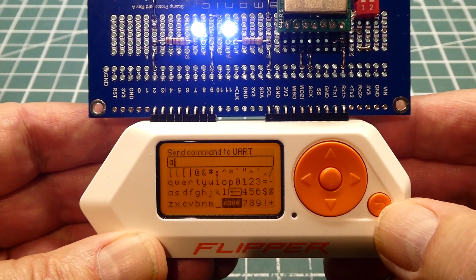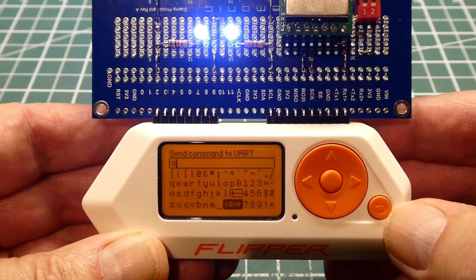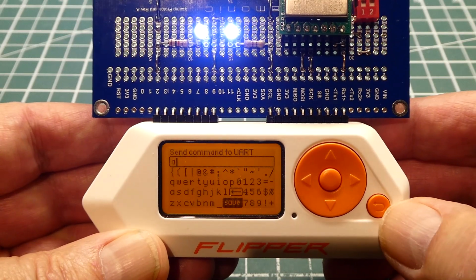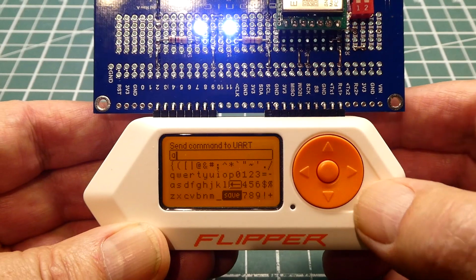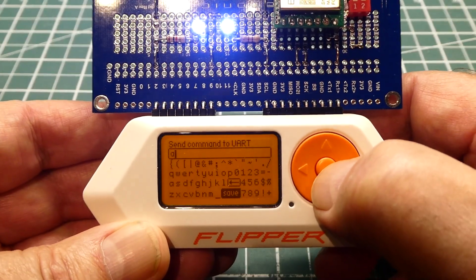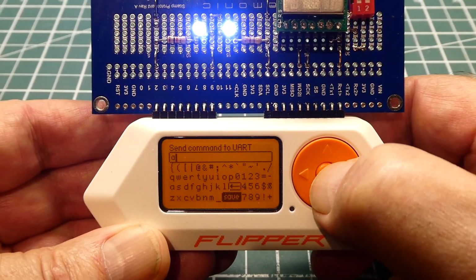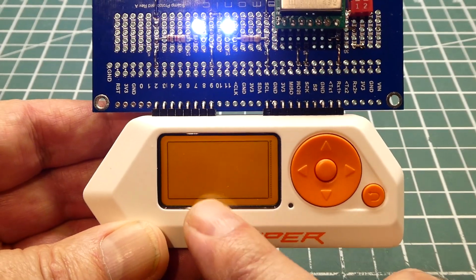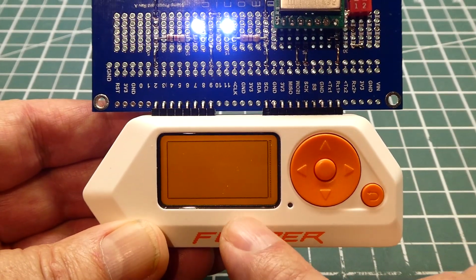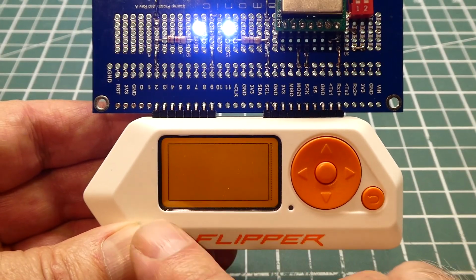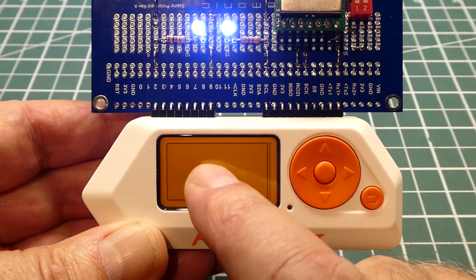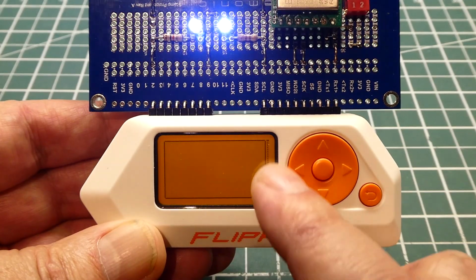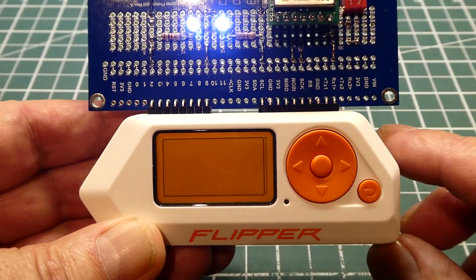Now in a normal remote control application, you usually have visual sight of the device that you're controlling and you get visual feedback. But if you're a long distance away, say a mile, and you send, say, a character, a code to turn on or off the relay, you send it. Now this screen here is the receive screen. So you could have the receiver send back an ACK saying relay on or relay off, and it will come on as text in this box. So this is your receive box from the UART.